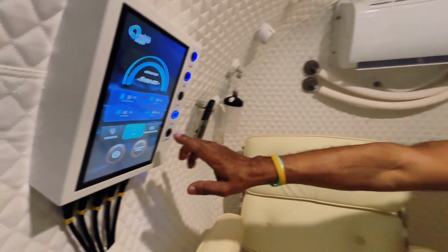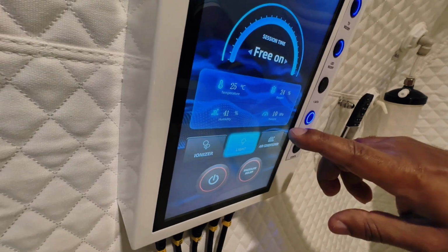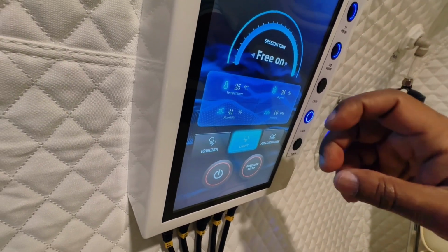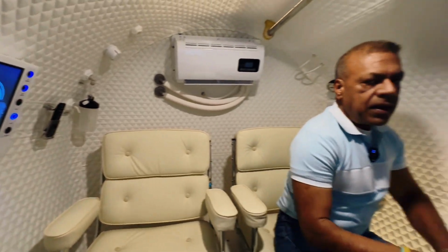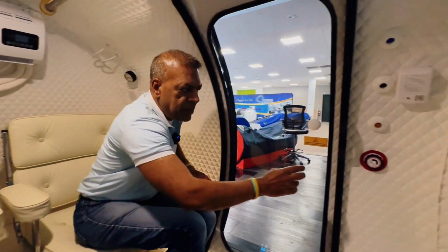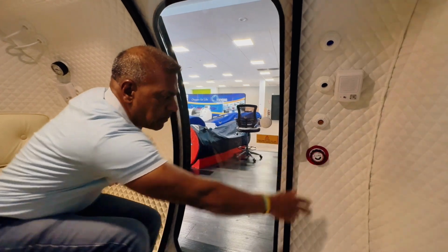So it's been about a minute since we began the depressurization process, and once the pressure reaches about, let's say, 10 kilopascal, that is the safe place for you to open up the valve all the way. So now let's just go ahead and do that. At this pressure, I feel completely comfortable opening up the valve all the way.